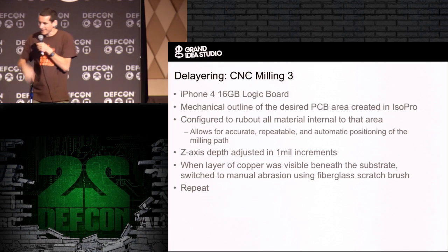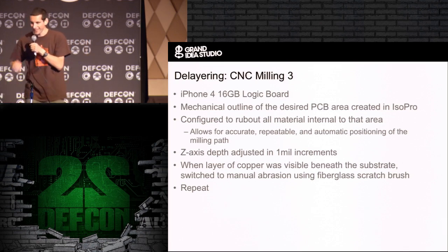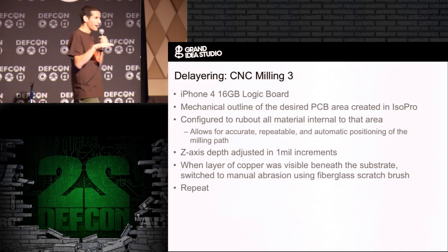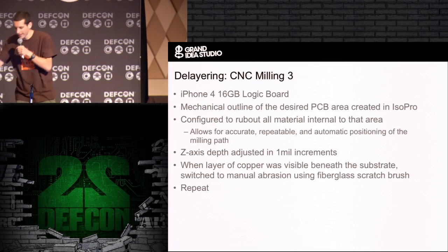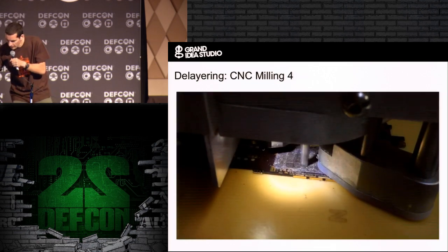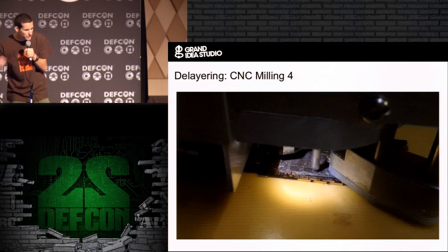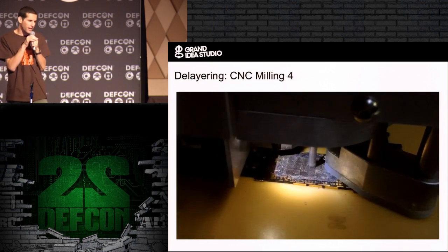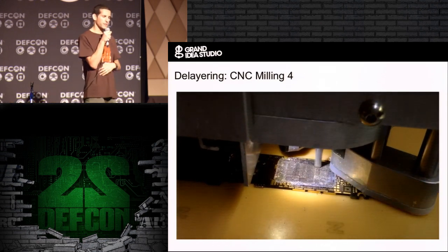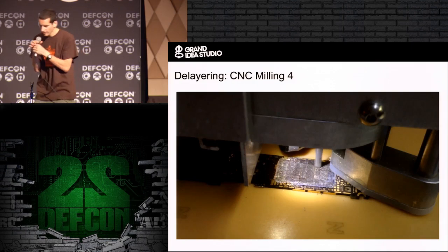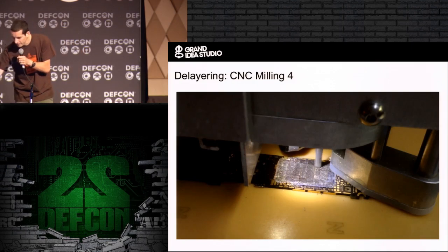So I'd keep doing the operation until I could almost see the copper, and then I would use a fiberglass scratch brush to do that really fine removal of the substrate. So here's a little video of just doing a little bit. I don't know how long this video lasts, but it's taking off just a super thin layer of that substrate. I did that for a few hours until I got it right.